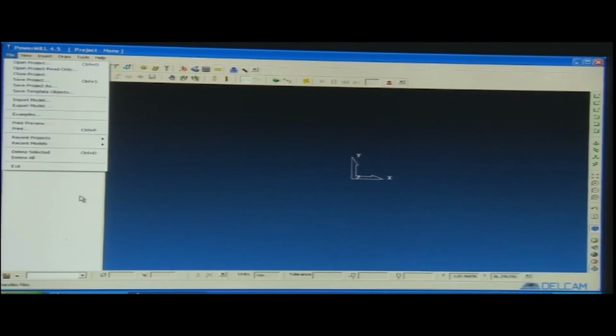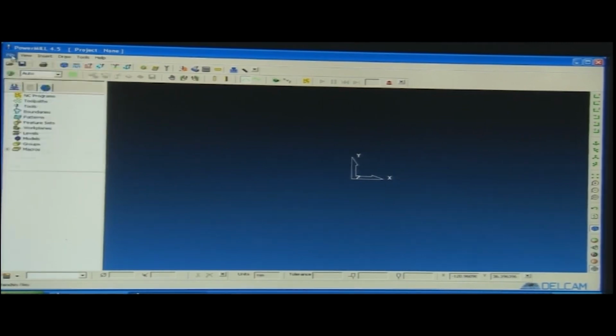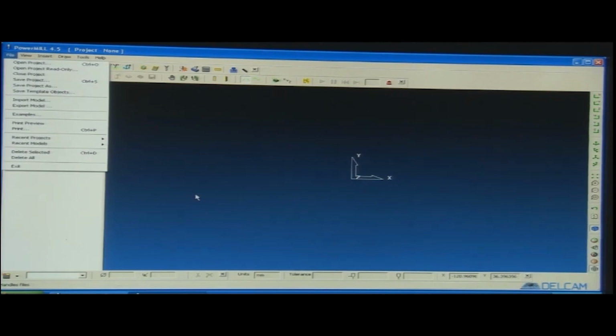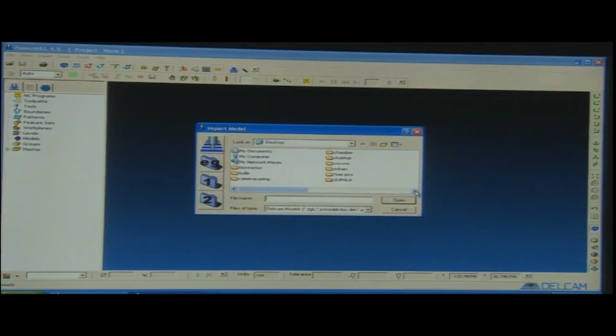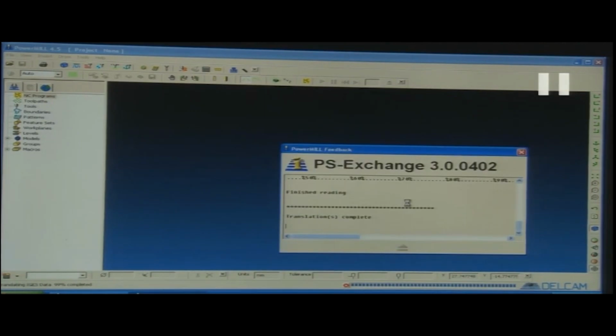The drawing, when I say the drawing, is the CAD, computer aided design. So, we can import the model for that. I go to this drop down menu option, import model. If I say import model, it will try to open the file. There are certain formats here, like we have IGS format, STP format, STL format. IGS and STP are generally used for CAD or computer aided manufacturing.